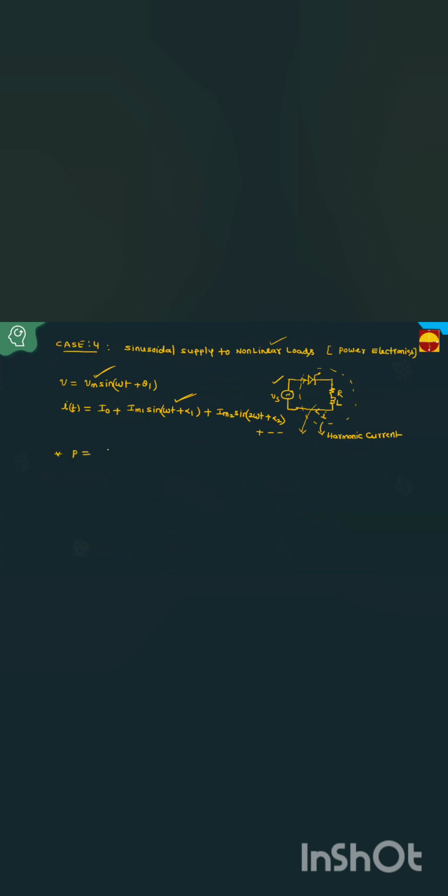P equal to, very important observation, sir. Listen. Here there is no DC term in the voltage, so in the power calculation we don't get that term. In this case, you always multiply equal frequency terms only. This we can get: Vm1 by root 2, Im1 by root 2, cos of theta 1 minus alpha 1. Remaining terms you don't get, because the voltage has only the fundamental component.